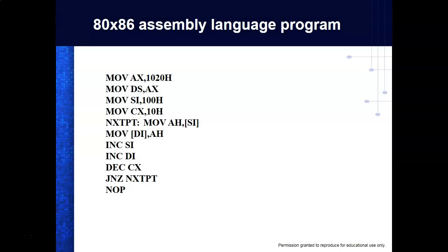So this would be an example. This is the same program written in assembly language. Now it moves toward, I know MOV, that would be the instruction to tell it to move something. And it's going to move the contents of an AX register inside the processor into an address 1020H, which is hex. Now, even though this is still very complex, I've got to know all the registers and the names of the registers inside the processor. And this was an Intel processor, by the way.